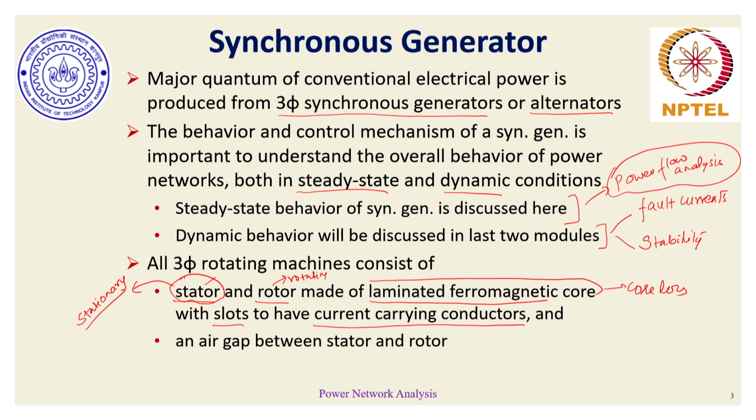Depending on the type of machine, these currents could be AC or DC for a general three-phase AC machine. In between the stator and rotor cores, there exists an air gap. Depending on the type of machine, the width of this air gap can vary. For larger machines, the air gap is larger, whereas for small machines it can be comparatively smaller, depending on what type of losses the machine can endure while not affecting its efficiency to the extent possible.